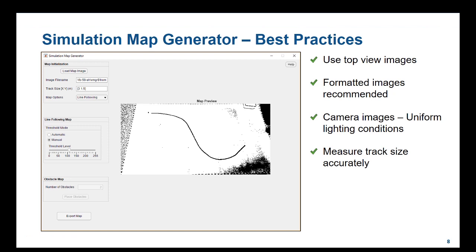This directly affects how the distance measurements are made in the map. Finally, make sure that the threshold value results in continuous lines and no breaks are introduced. It is okay to have some disturbance if it's not in the direct field where line following happens. Now that we have set up the simulation, let's implement a line following algorithm and see it in action.